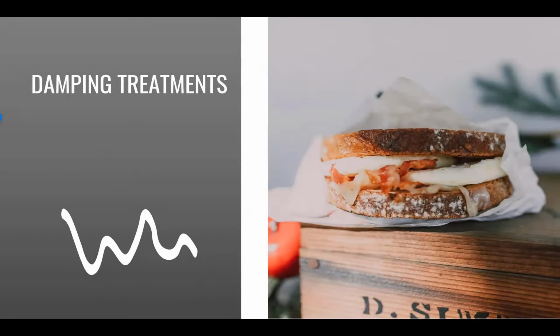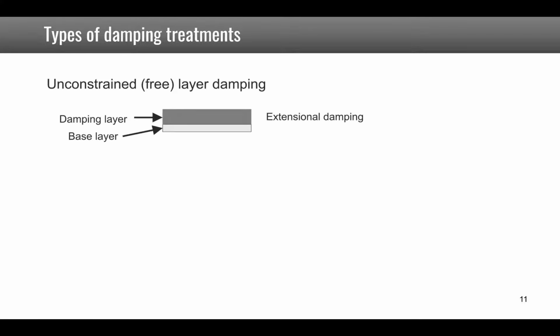It's also possible to increase the level of damping due to materials by using some damping treatments. There are two main types of damping treatment. The first one is referred to as unconstrained layer damping. The idea is that you have a base layer here of a material which has quite low damping, and then you add or glue to it a damping layer. So this is made to function either in traction or in bending, which also induces traction here. And so the damping layer here works in extension.